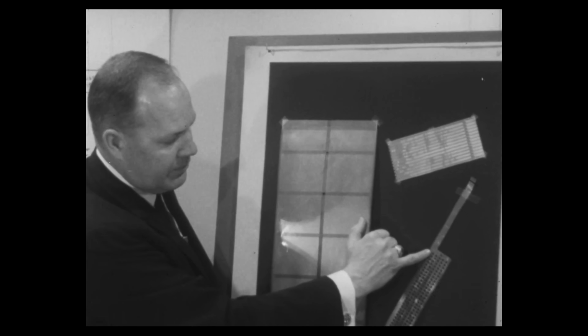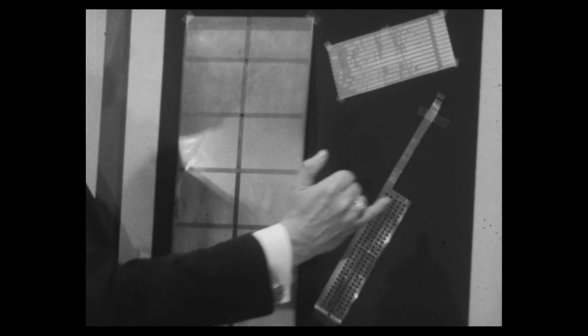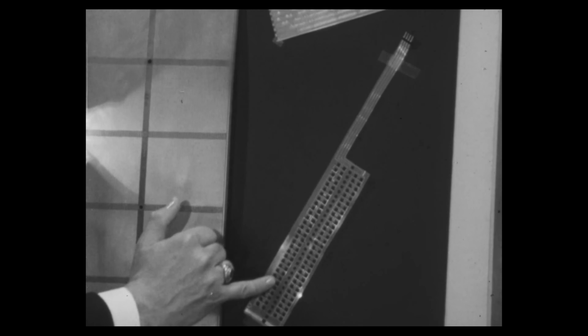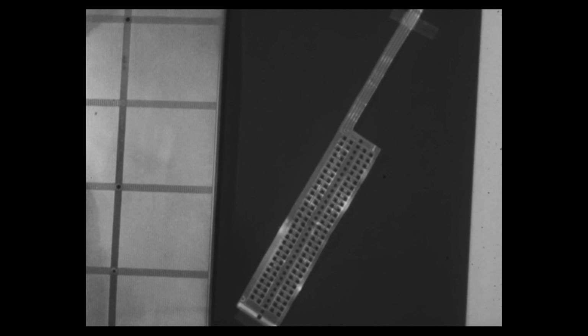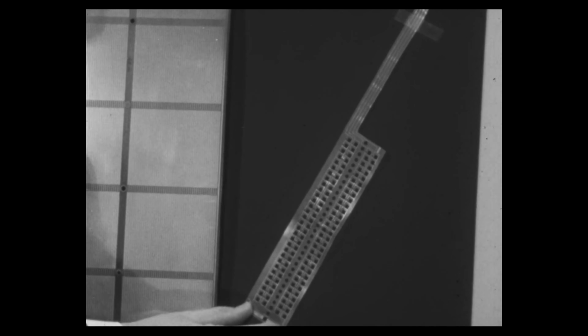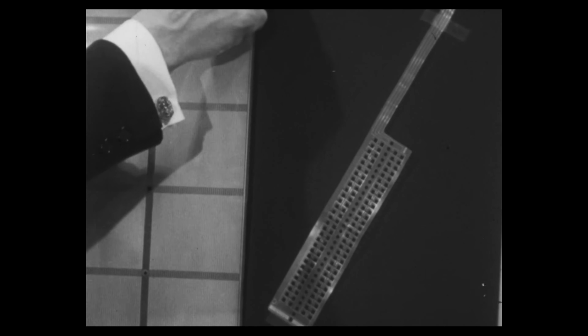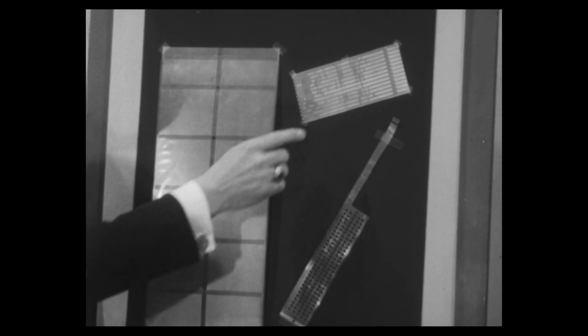In the case of the Model 40, a microinstruction word is comprised of 60-bit positions. The outside row forms one word, the inside row forms another word. So each of the tapes in a Model 40 has 2 micro words. Each of the cards in a Model 30 has 12 micro words.